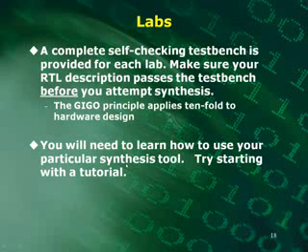I'll talk a little bit about the labs you're going to be doing for this lecture. There's a completed self-checking test bench provided for each of the labs. I want you to make sure that your RTL description passes the test bench before you attempt to synthesize. The garbage in, garbage out principle applies much more when you're trying to actually produce hardware.